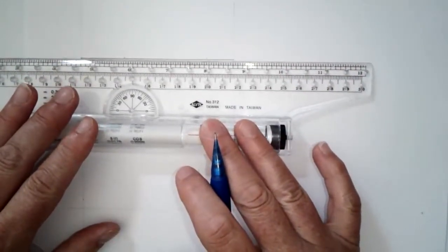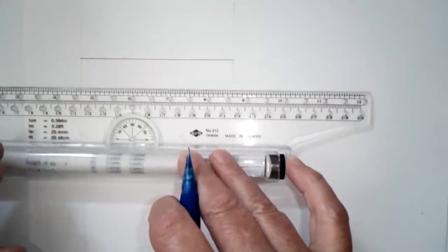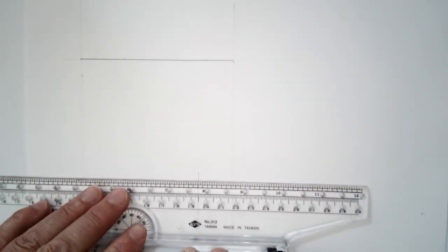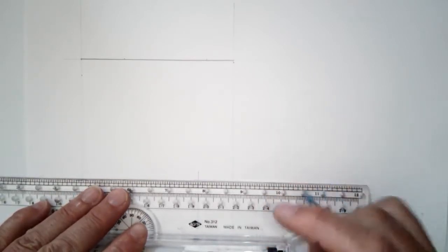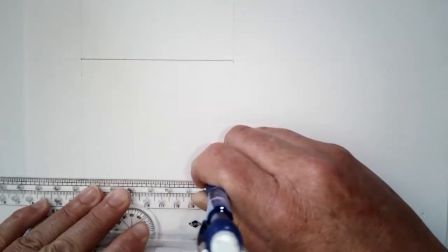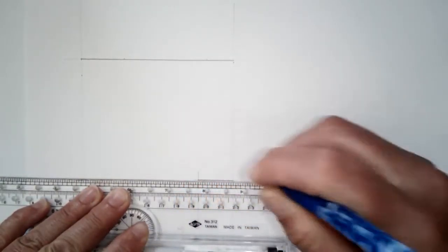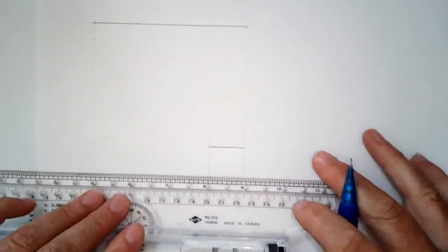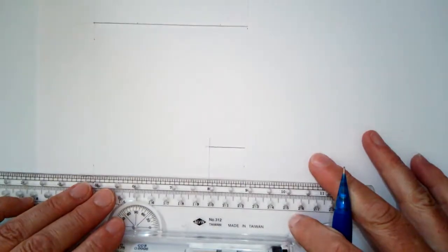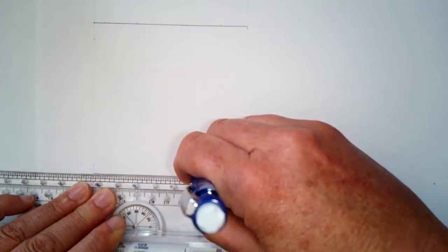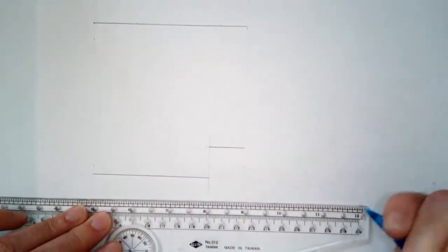So since I'm already in this horizontal position, let's mosey on down to the next construction line I have that's also in a horizontal position, which happens to be this feature right here, and put in that feature. I know exactly where to start and stop that line because of my construction lines, and I'm not worried about it. And then we'll roll it down even further to the last horizontal line that I have and draw that line across. So now I've got the consistent line weights for all my horizontal lines.